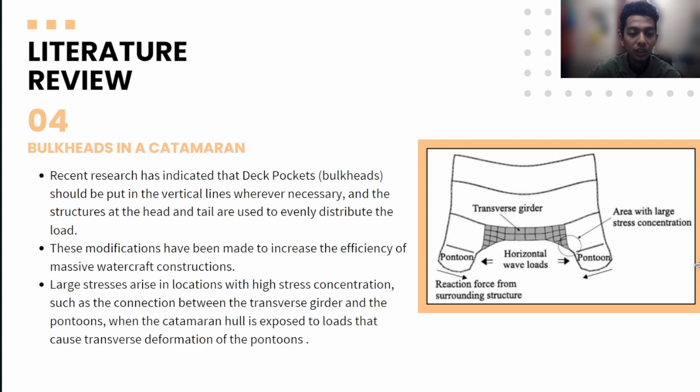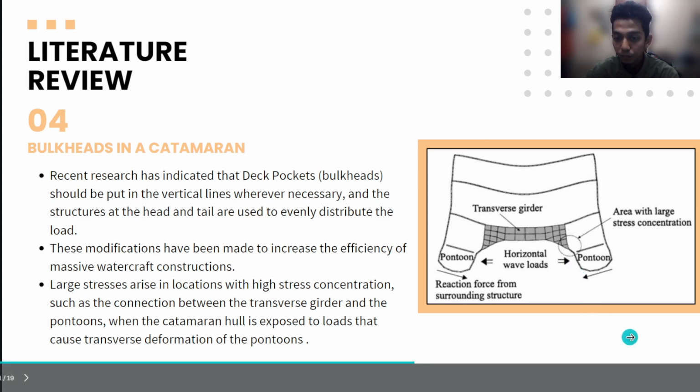Large stresses arise in locations with high stress concentration, such as the connection between the transverse girder and the pontoon, when the catamaran hull is exposed to load that causes transverse deformation of the pontoons. Here we can see the transverse girder, and the horizontal wave loads will act on the pontoon. Here is the reaction force from the surrounding structure.